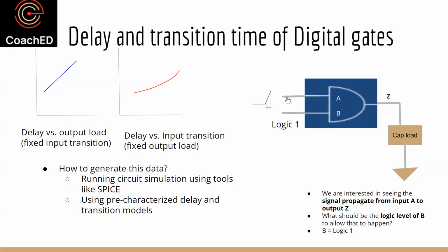For example, as I was showing yesterday, we have a relative delay between data and the clock called setup time, which means you will have a setup arc, a data to clock arc. And then you could also have a clock to out arc. If it's a flip-flop, that's an output arc, just like a combinational arc. So sequential elements will have 2 sets of arcs, between the inputs and also from input to output, while for combinational gates the major arcs are from input to output.